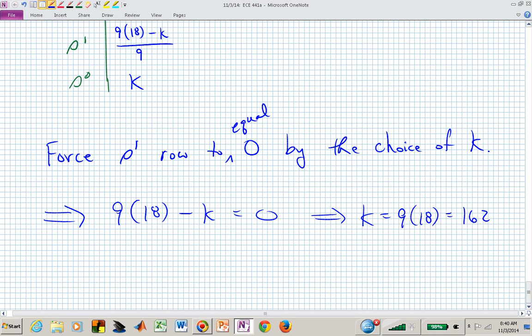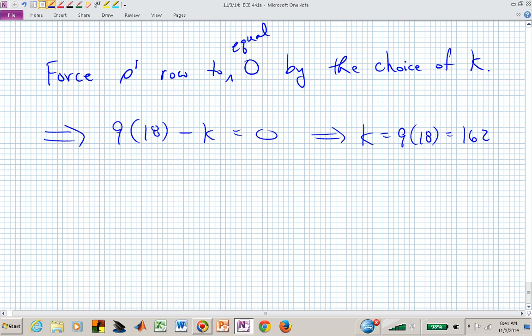Now if somebody says, oh, put in a gain of 170 because I know that's really going to make my steady state error small. You go, wait a minute. Don't crank it up to 170 because then you're going to drive your poles into the right half plane. You'll have an unstable system. You won't even have a steady state error. So you go, wait, why don't you keep it below 150 just to be on the safe side? Because we know after lab 1 and 2 that your model may not be that accurate that you've maybe experimentally determined. Maybe it's good, maybe it's not. But you have to live with what you can determine from the data.